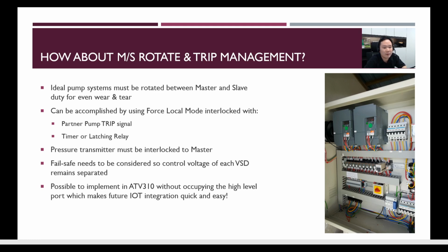And there are so many failsafes that you need to consider so that the control voltage of each VSD remains separated. So in my example just now, if your sensor requires a 24 volt loop power, don't mix them together, because we don't know what happens when one of the VSDs, probably the control voltage 24 volt, shorts to earth, something like that.